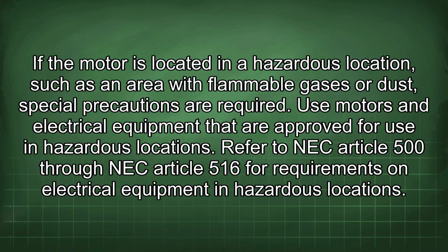If the motor is located in a hazardous location, such as an area with flammable gases or dust, special precautions are required. Use motors and electrical equipment that are approved for use in hazardous locations. Refer to NEC Article 500 through NEC Article 516 for requirements on electrical equipment in hazardous locations.